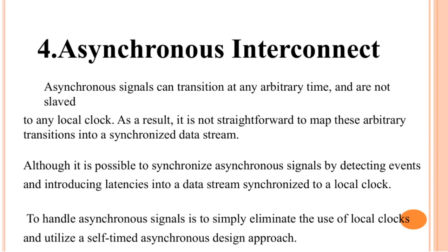Here we are looking at asynchronous interconnects. Unlike synchronous signals that are tied to a local clock, asynchronous signals can change at any random time. They're not controlled by any clock signal. This makes it challenging to convert these unpredictable transitions into a neat, synchronized data stream.